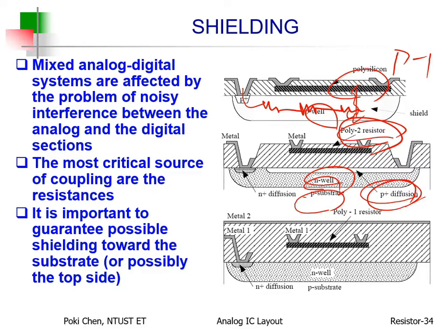According to the second chapter on the manufacturing process, I told you, for such kind of polygate, I mean poly1, right? It needs to be fabricated earlier than your source and drain. P plus or N plus means the source or drain for your MOS, for your PMOS.